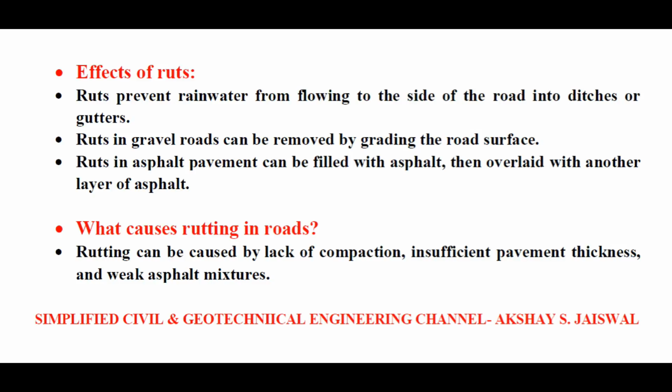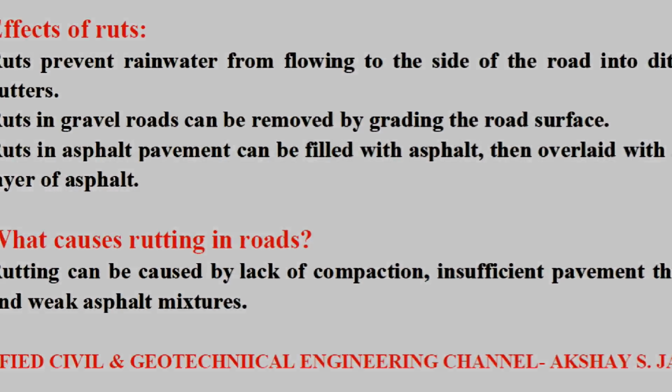Now we will see what are causes of rutting in roads. Rutting can be caused by lack of compaction, insufficient pavement thickness, and weak asphalt mixtures.